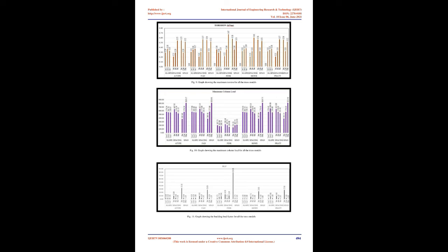Moderate span length served as economical for the bending moment to be minimum, for plan aspect ratio 1:2. Fink truss possesses comparatively lesser bending moment. Truss is subjected to torsion irrespective of the span length, rather say a very negligible level of variation is induced in torsion when span length is changed.